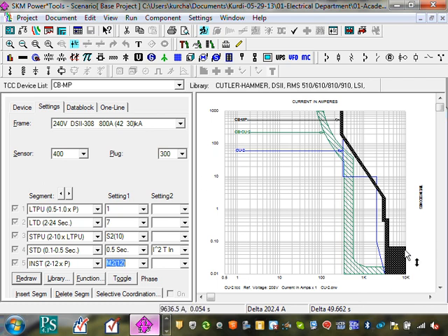So here's the, can you guys see that one here? Now I'm reducing it. This is how you adjust these circuit breakers. To make it easy, how many of you guys have seen these? The nice thing when you do overcurrent coordination, when the engineers charge you an arm and a leg to do that, it's hard to look at numbers and compare them together. It's harder to look at numbers than to look at graphics.